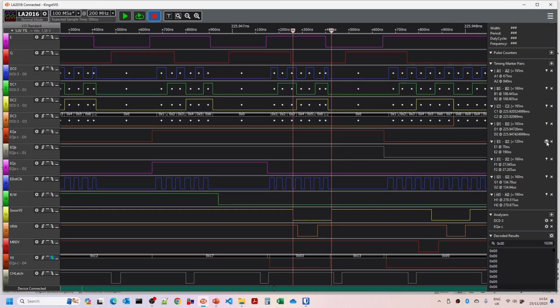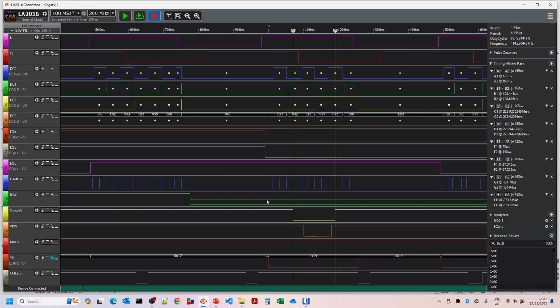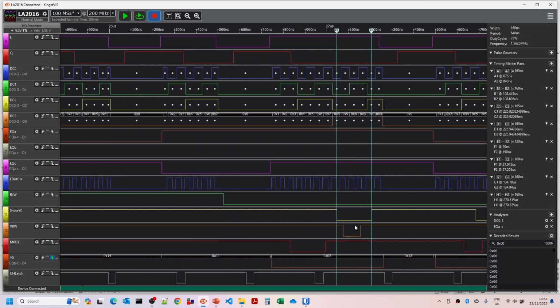So then have a look at E. So this should be 4, and this required a little bit more messing around, but this is slightly different from the other previous two, and I'll explain that in a minute. So we look at F. It's 05 here, and this does have a memory ready signal here, and we can see that it's extended, and that in fact our clock cycles here is between about 7, 8 and 11, 12.